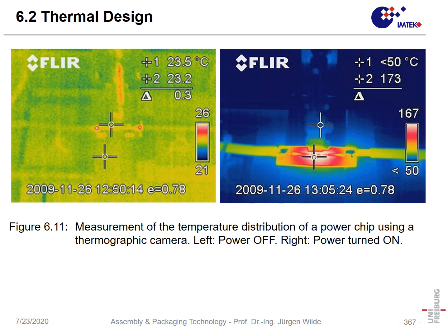Let's have a look at the thermal image. For instance, that is a small power device we had in an infrared camera. And you can see the camera is turned off. We have just a very small radiation. So maybe there is a very small power dissipation in that device which is in idle mode.